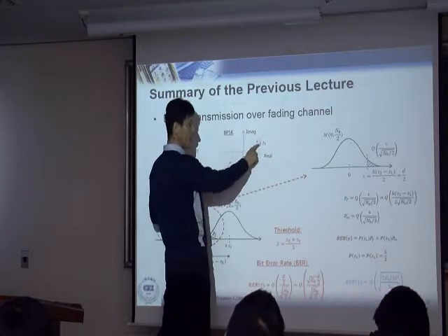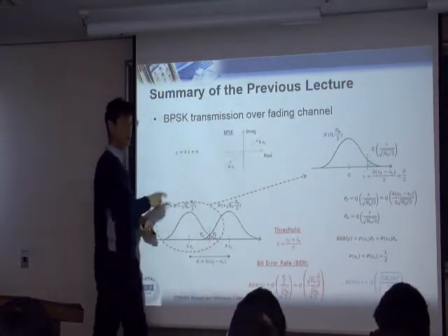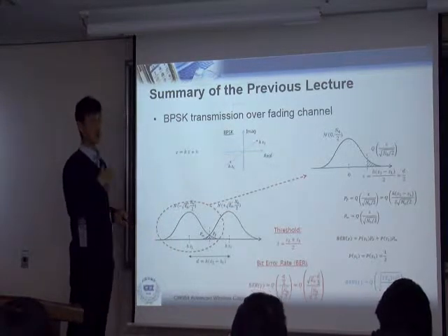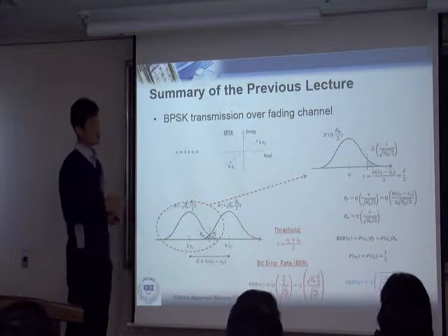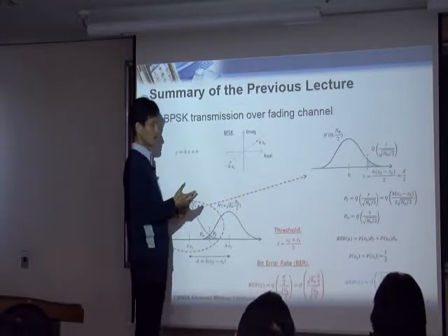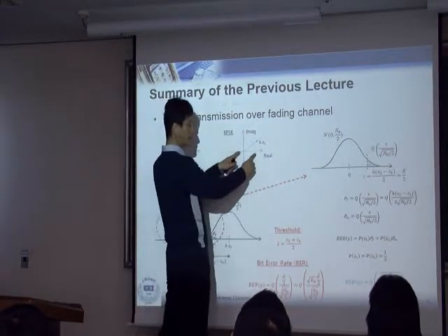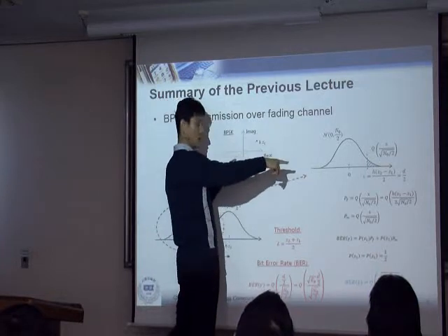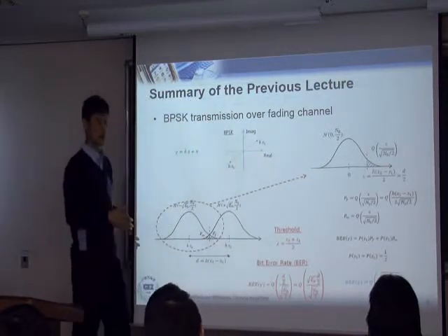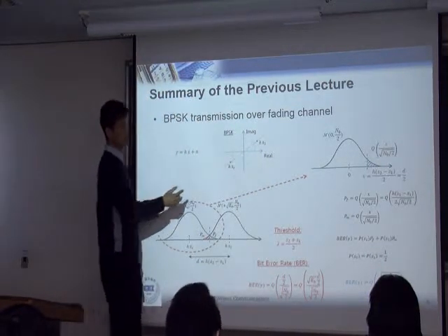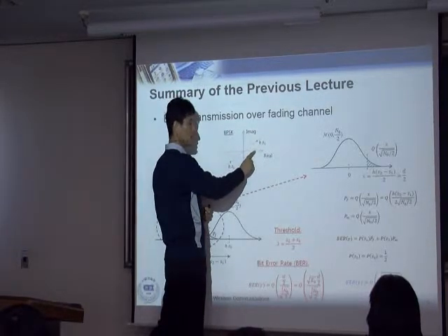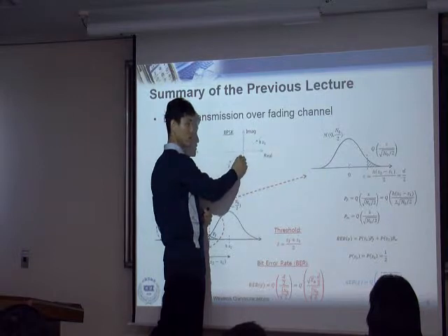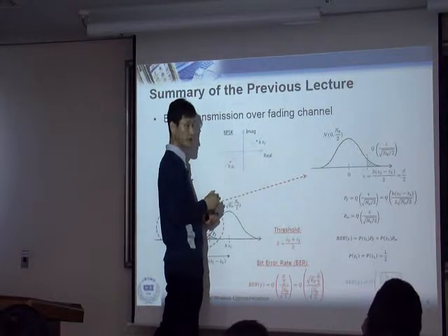But now this fading H follows fading channel statistics, for example a Rayleigh channel. So what is a Rayleigh channel? Rayleigh channel basically has this amplitude PDF, right? So when you go through the Rayleigh fading channel, typically the amplitude is getting reduced with a certain high probability.